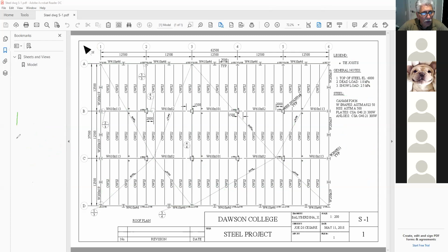So, for example, if you're going to have some kind of a gusset plate here, like this, how are your holes? Are they like this in your gusset plate, or are they like this? Yeah, they're like that. Okay, so if that's it, then you're going to have to check the tear out here instead of the block shear. That's all you have to check. Make sure you have an edge distance here, at least 35 millimeters, whatever you need, and then this spacing here. This is in tension. This here is in shear. And therefore, you can calculate the long equation exactly.